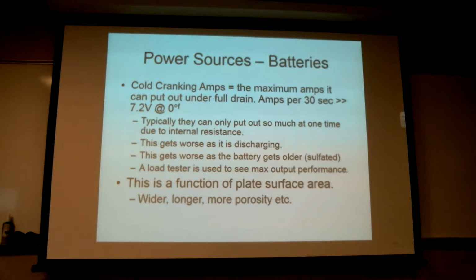So how many amps will it put out? There are other standards, unfortunately. So when they say cold cranking amps, one battery manufacturer might be doing something slightly different than another. But it's fairly typical to see a value like 350 or 440 cold cranking amps. What they're really trying to say is, will your starter go wah, wah, wah, bum, and start things up when it's really cold?